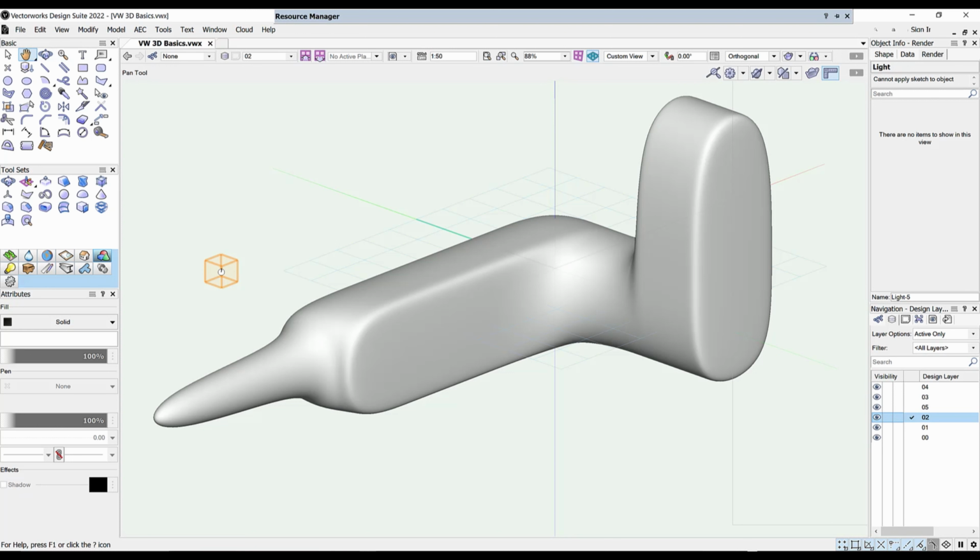In my last video, I did an introduction, a part 1 of the subdivision modeling feature, and in this video we are going to move on a little bit further into some of the other modes that can be used in subdivision modeling. In case you are new, subdivision modeling is a form of modeling in which a 2D geometry is represented by a polygonal mesh comprising smaller faces, edges, and points. The higher the number of subdivisions, the smoother the object gets, allowing you to model much more complex organic forms way faster than the traditional way of modeling.